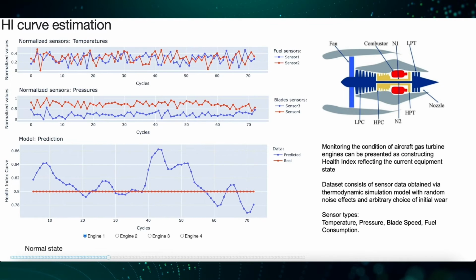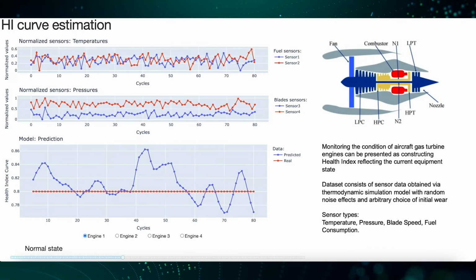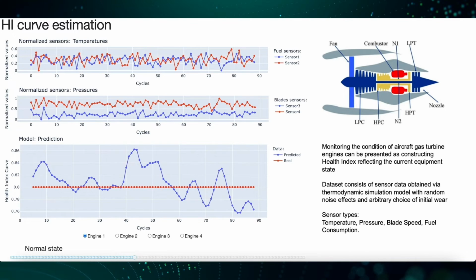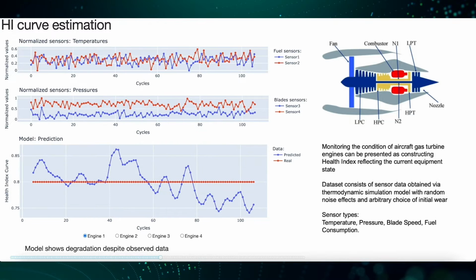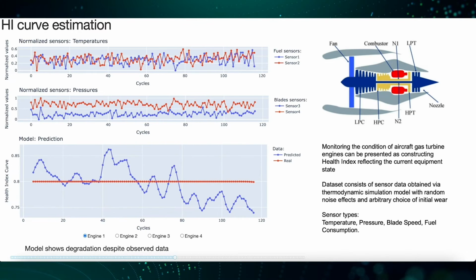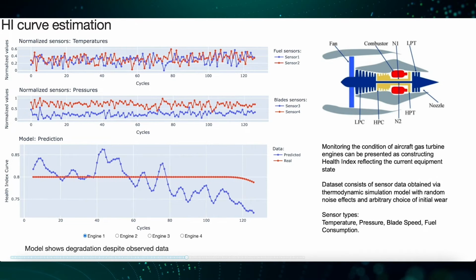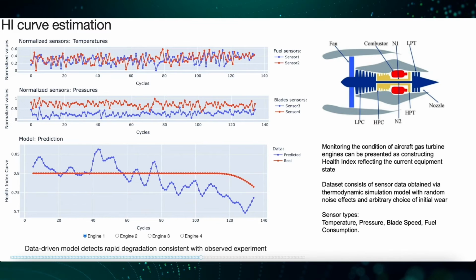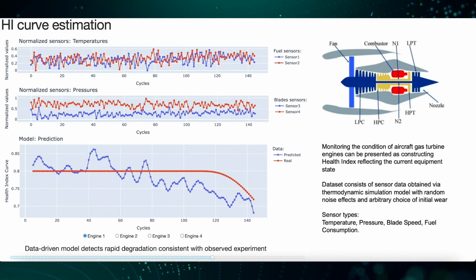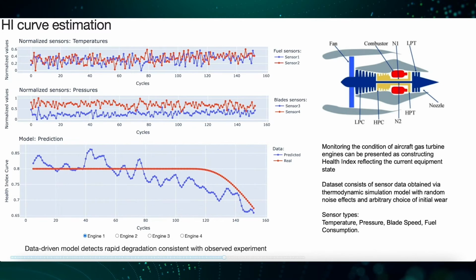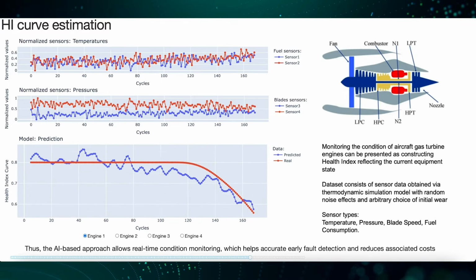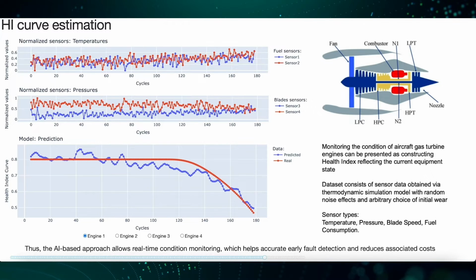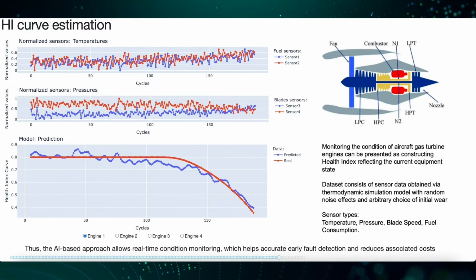Showing the neural digital twin for estimating the condition of airplane engines. The demonstration is performed on NASA's C-MAPSS dataset. The developed model makes a prediction based on 25 sensors of internal engine parameters. Several of them are shown in the corresponding graphs. The built model demonstrates the possibility to register engine degradation on the fly and allows to conduct more accurate data-driven condition monitoring, which is the current aim in the field of industrial AI.